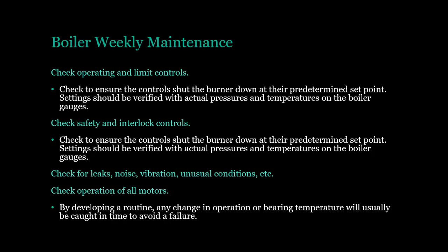Check for leaks, noise, vibration, unusual conditions, etc. Check operation of all motors. By developing a routine, any change in operation or bearing temperature will usually be caught in time to avoid a failure.